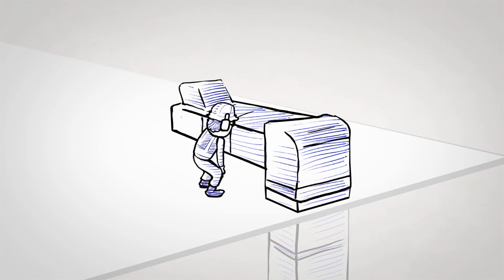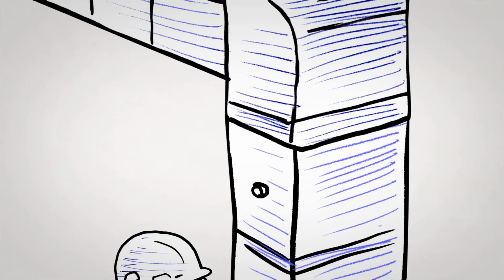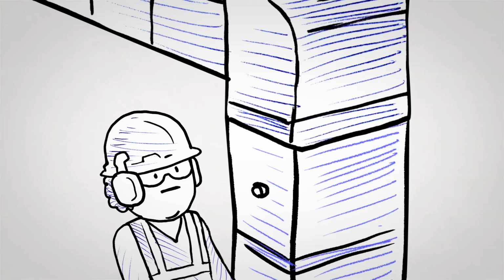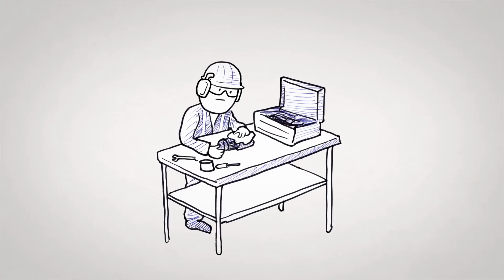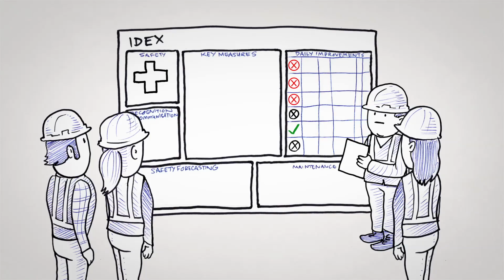He noticed the level in the conveyor discharge spout was not high, so he safely shut down the equipment and inspected the high-level switch probe. It was dirty. After cleaning it, he concluded the production loss was due to a dirty transmitter. The next day at IDEX, he shared his findings and 5 why.